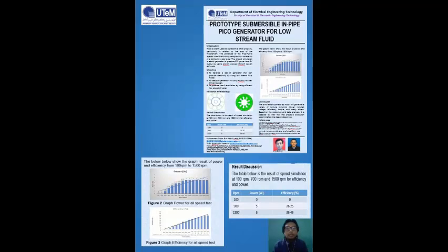You can see on the screen the different efficiency in the figure graph. For the 15 speeds that have been simulated, the efficiency differs for different speeds, and at 100 and 200 rpm, the efficiency is 0 because the motor cannot produce output for the lack of speed.